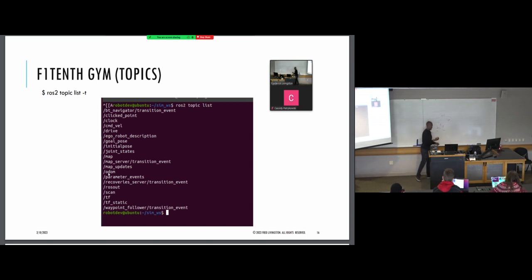But you can see that has some error in your system. Are you describing the topic or odometry in general, and how it works in the ROS environment? Or in pretty much anything: it's taking the velocity and converting it to position. If I'm moving at 1 meter per second, I look at the time I move and can compute the distance from there. But your clock is not necessarily accurate, so your odometry is not necessarily spot on. It does have a lot of error in the odometry information, so it's going to be less accurate than using your laser scan. But that is the odometry message.